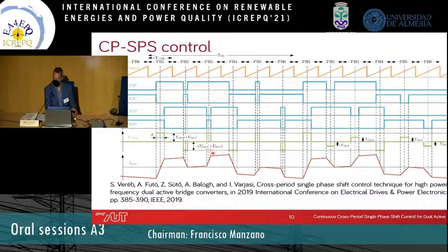So what we can do by switching is create an inverted voltage across the transformer leakage inductance, or we can short one side of the transformer for a short time. Then it will create a lower pulse voltage. So we have multiple options to choose from. What is the problem with this?